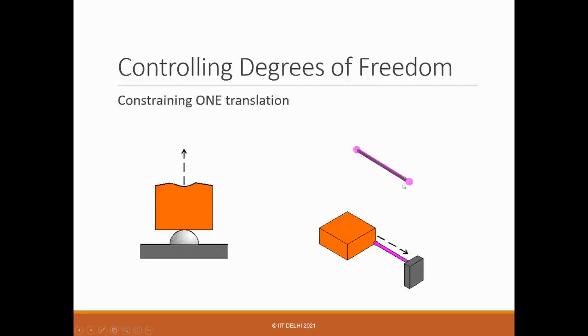So what you realize in this case, again the axial stiffness, the longitudinal stiffness is EA by L, which is much higher than the bending stiffness and the torsional stiffness of this wire. So in that case, we call it wire flexures.